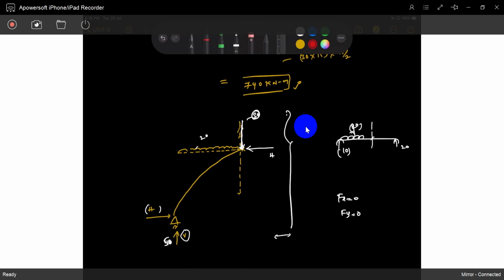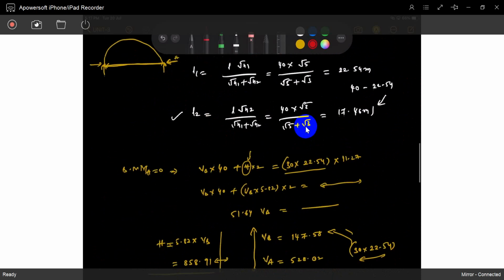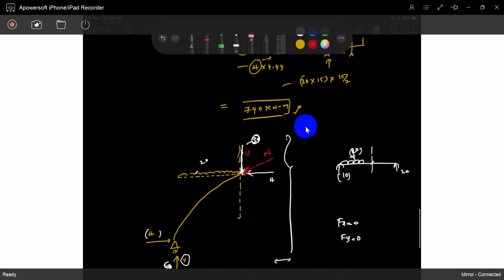But if you observe, we distribute the loads in the direction of the arch. That is the normal reaction, so we can call it the normal thrust. You can divide this V and H into the normal direction, and also V in the direction of the arch. Normal means normal to the surface of the arch.